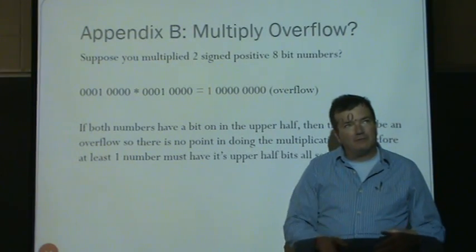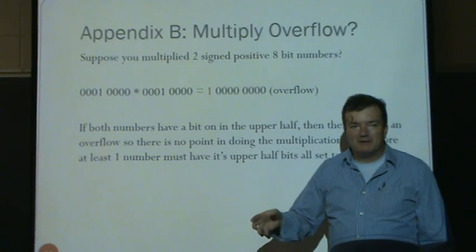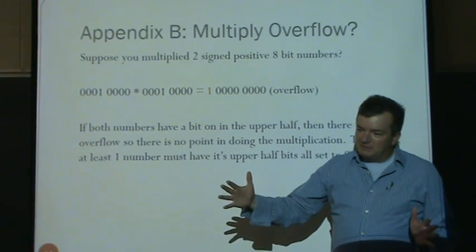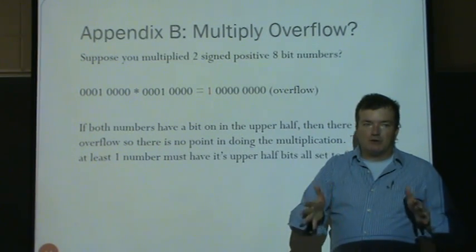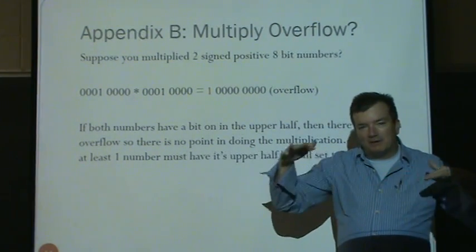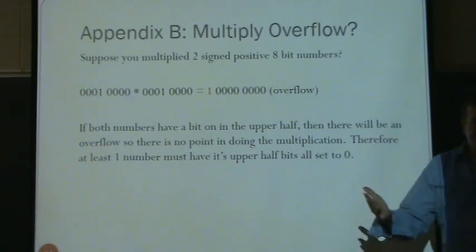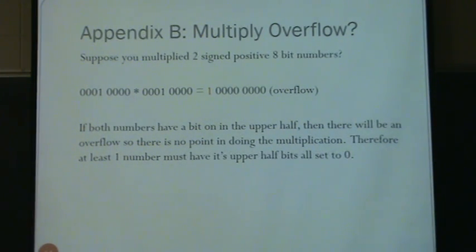It comes down to about 5/16 of the number of bits. So if you have 32 bits, the worst case scenario is you're only going to have to do 10 adds before you're done. And so we could build a circuit that would be a lot smaller than what originally meets the eye.